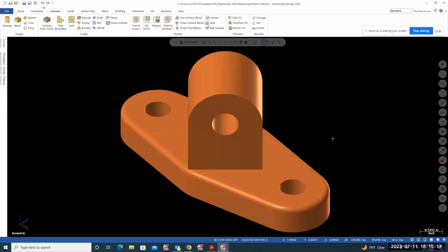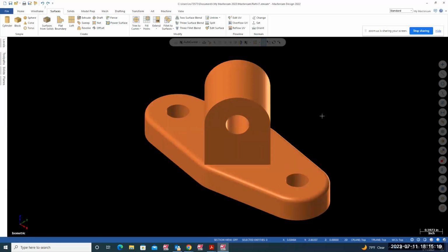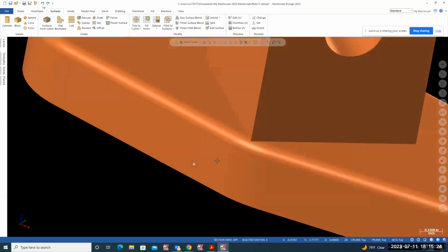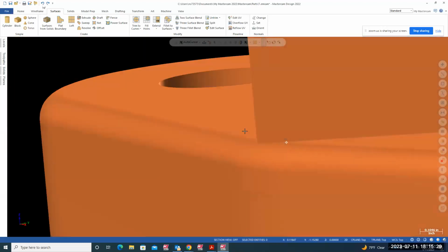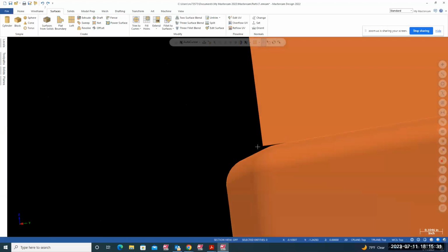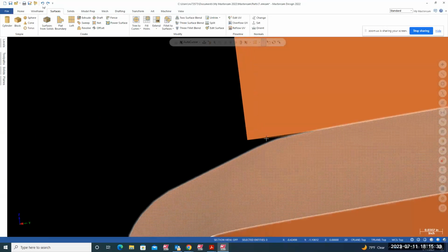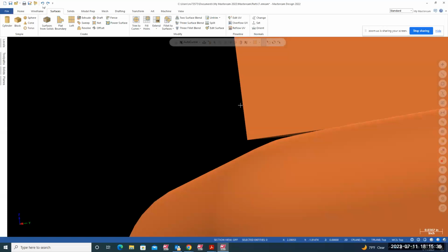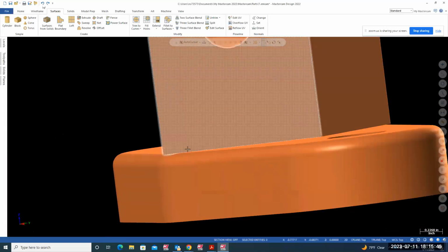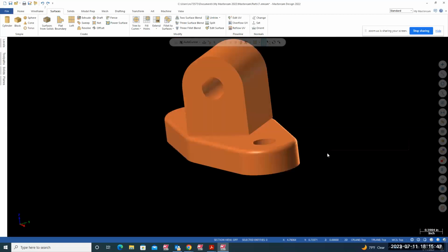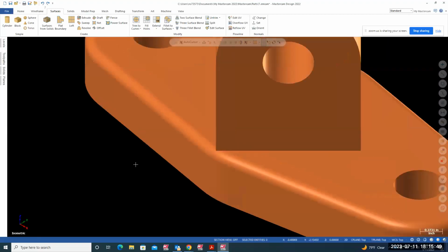Isometric. Because you cannot get this fillet on the bottom until you get this corner fillet, because this is going to blend with this over here, guys. Look at this, how that fillet is separated from that. So we have to make that fillet first. Then this is going to blend with this fillet right here, the corners. So this has to cut first, this corner, the one we are doing right now. Okay, one more time.